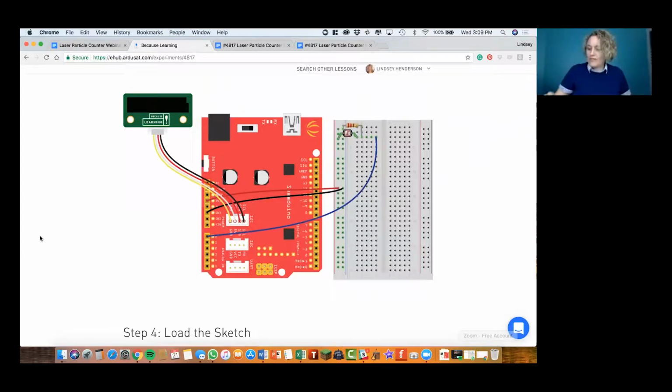Okay, let's start with the Arduino. Let me get it oriented right. So from our diagram on my screen, we need 3 wires. We need a red wire, and color doesn't really matter. The color is just, traditionally we use the red wire to come from the power. And in the wiring diagram, that's exactly what it is. The red wire is going into the 3v3 port.